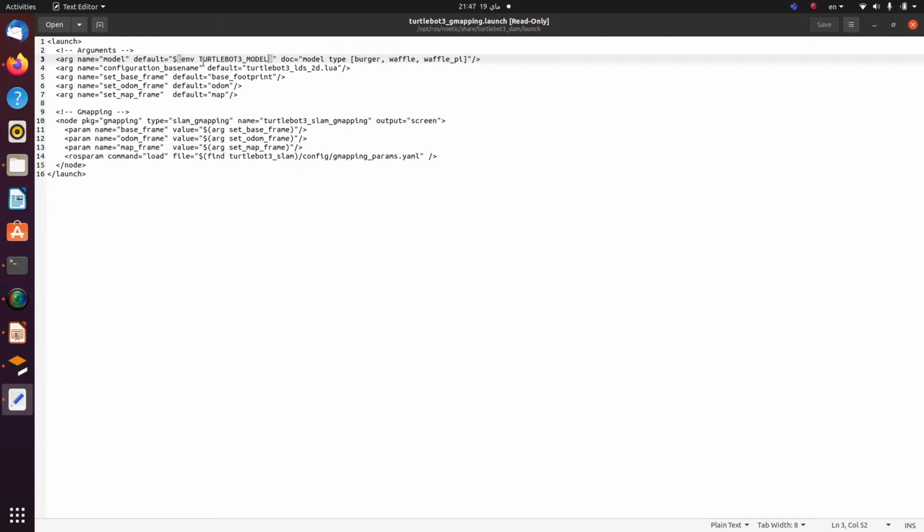So you've got geometrical differences. So you need to determine your model in order to have the proper transform that's going to transform the LIDAR readings, right, which are referenced to the origin of the LIDAR itself, or the frame of the LIDAR itself, to the frame of the robot. All right. So the LIDAR frame does not have to be coincident with the robot frame, and this is one of the differences that you have to bear in mind. All right.